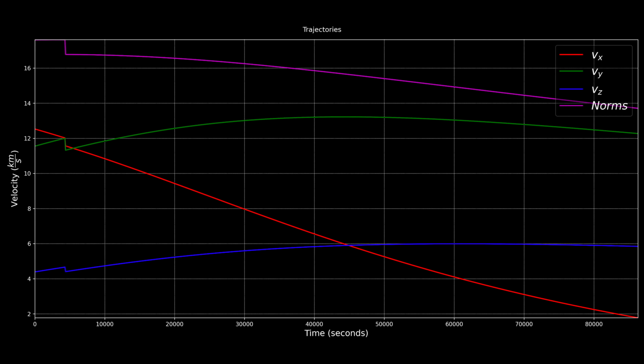First, we need to find when the Jupiter orbit insertion burn happens using the published Europa Clipper trajectory data in the form of a SPICE kernel, which we can do by taking a look at the time history of Europa Clipper's velocity vector when arriving at Jupiter, and we can see the discontinuities here, which is marking the burn. And also note that this burn reduced Clipper's velocity with respect to Jupiter in order to capture into an elliptical orbit.